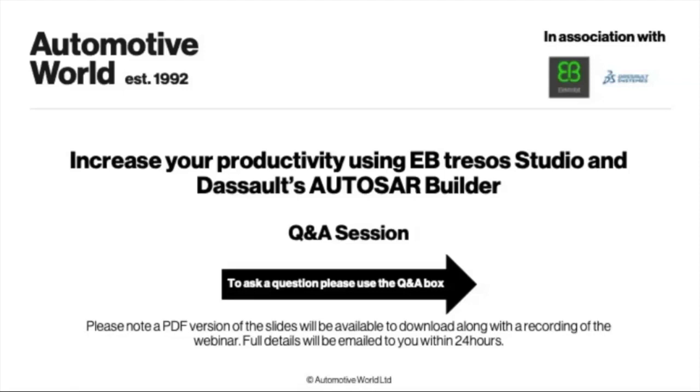The reason why there's also an RTE contract phase in AUTOSAR Builder is because this is the place where you actually develop your application software. So once you've developed your software component in AUTOSAR Builder, you can directly generate the RTE contract phase from there. So don't mix up the contract phase with the full RTE generation. We're really talking about the contract phase, which is generating the header files. Of course, what you could also do is develop your software component description in AUTOSAR Builder, import it into Tresos Studio, and use the RTE contract phase generator there. So this is up to you.